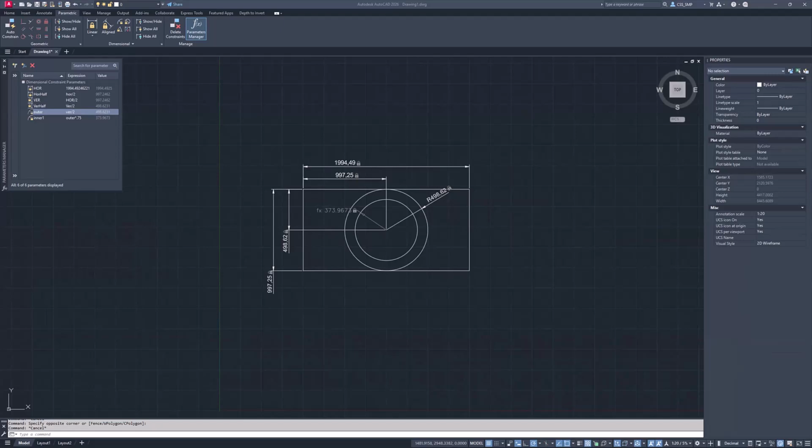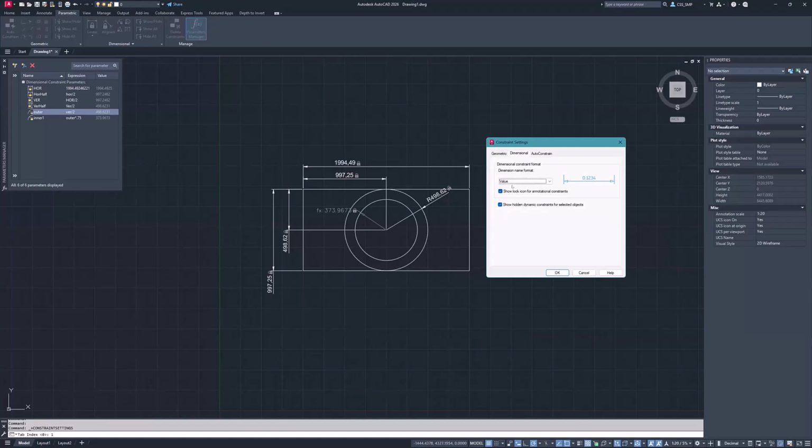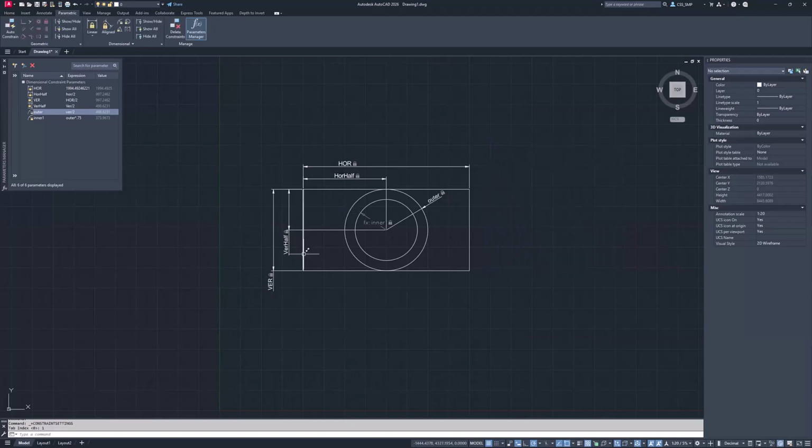Yeah, there are a series of questions. Some I've answered either by writing back or giving you the time to fill out. So there was one question that if the dimension constraint is set to annotative, can we get rid of the variable? You know, horizontal equals. Yeah, up here with the settings, just setting the value name, value only. So if you did name, it would be whatever the expression is that we've used.